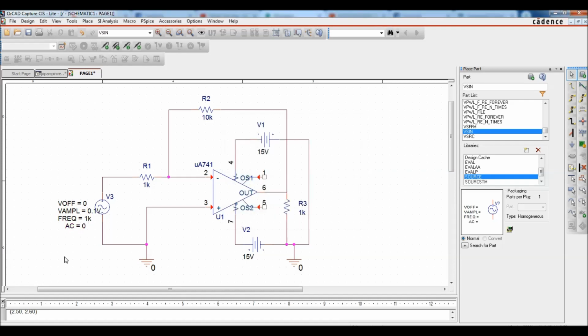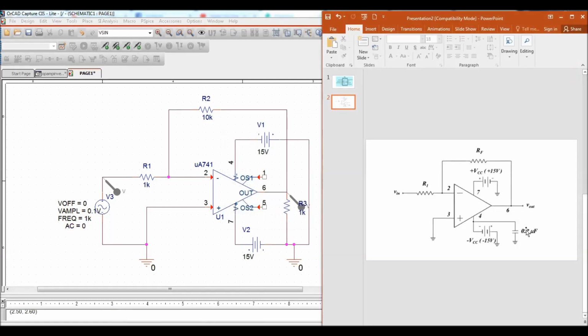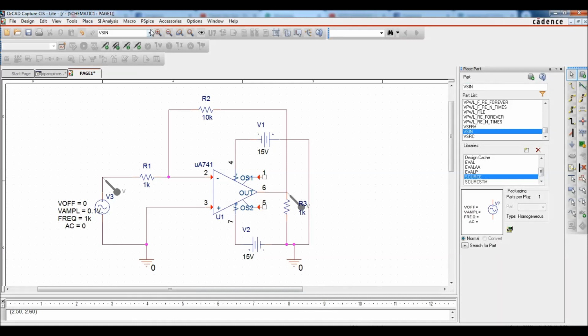Okay, right. So this capacitor here, I can include this in the schematic, but because it's just a schematic and I just want to simulate, I will choose to not put this here, because the capacitor here is actually for you to remove the noise. This is what you're going to put in the hands-on experiment, but for the simulation purpose I'm not going to put this capacitor. So I think I'm ready to simulate.